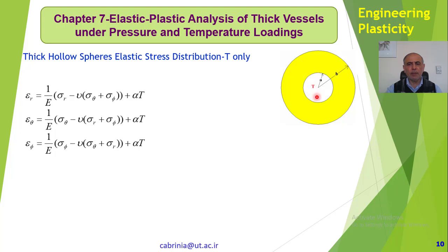Inside it is empty. It has a wall thickness which is comparable with the inside radius, and we considered such a sphere under the action of internal pressure, and we derived the stress distribution, strain distribution, the displacement relationship along the radius, and also we developed some relationships for the incipient yielding, which we determined that it happens at the inside wall.